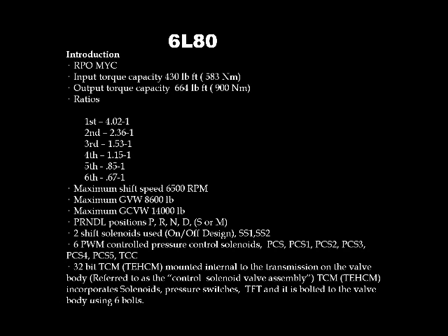The electronics on the transmission are quite sophisticated. You're going to find that we've got 2 regular shift solenoids. Those shift solenoids are called shift solenoid 1 and shift solenoid 2. Those solenoids, guys, are primarily used to move the car forward or backward. They don't have anything to do with making the transmission actually shift. So if you've got a car that won't move one direction, you typically will have a failure with one of those 2 shift solenoids, because one is in charge of moving the car forward, one's in charge of moving the car backward.